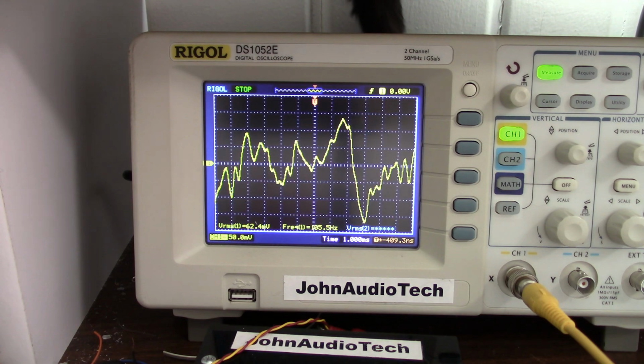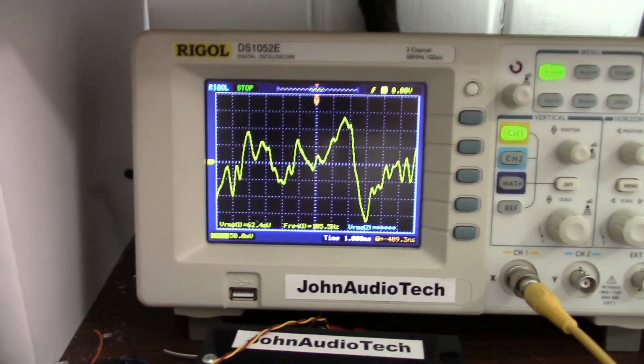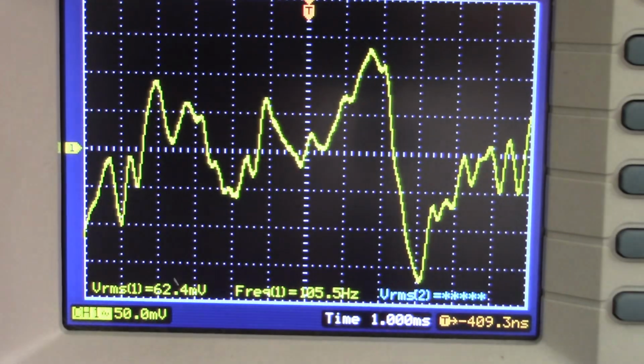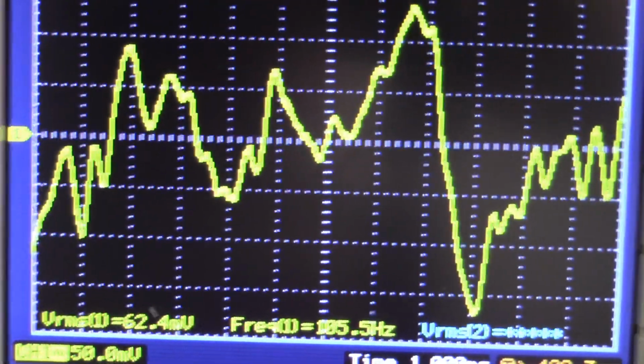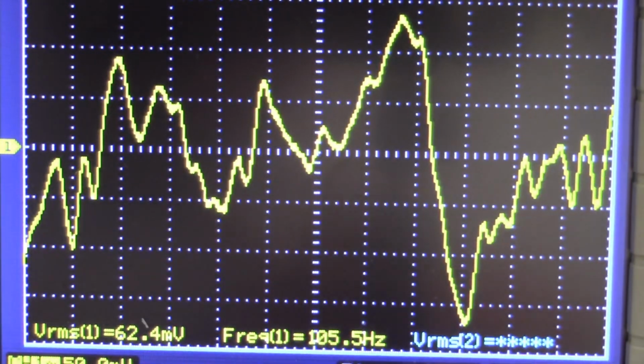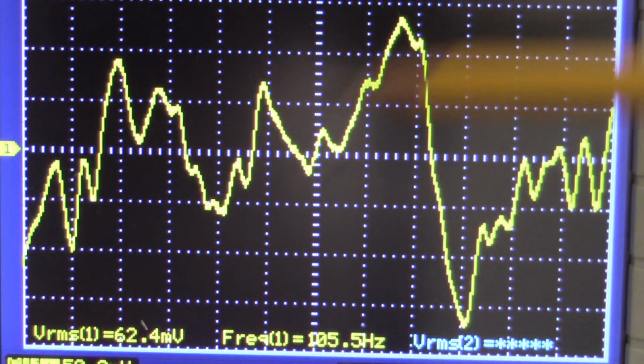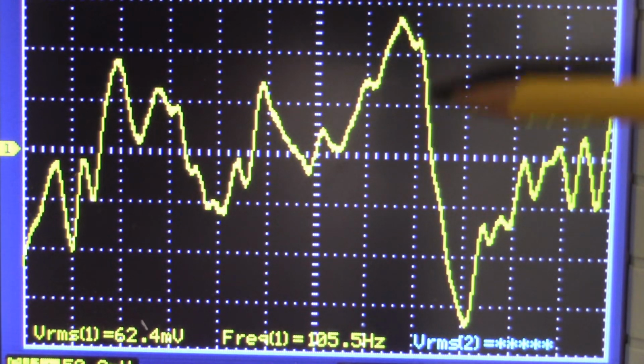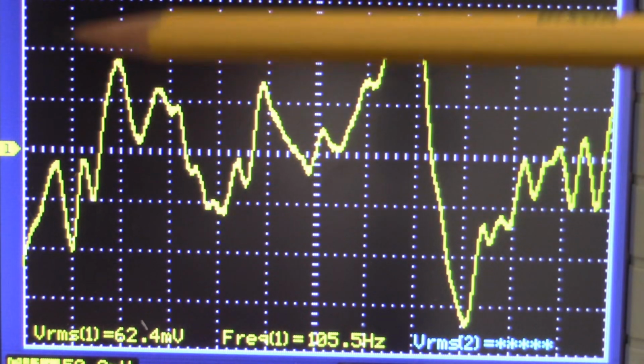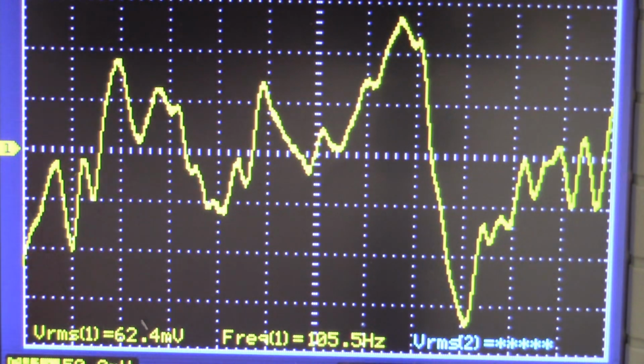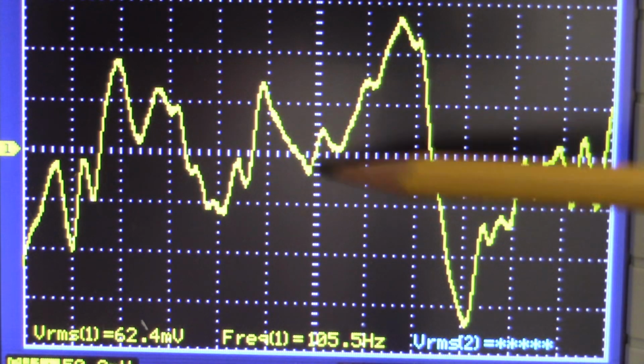They're all uncompressed WAV files, so they're high quality. They were digitally synthesized, so there was no conversion going on there. I did have one person make a comment in my video about digital being stair-steppy. Like if I zoom in here on the oscilloscope screen, you can see that the file does have little steps to it. It's not perfect, it's little stair steps. That has nothing to do with the actual WAV file. That's just the resolution of my scope screen here.